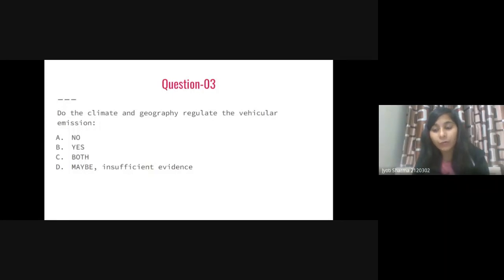But if you have lower temperature, then your NOx will be reduced, but your carbon monoxide will be higher, because there may not be sufficient combustion, like there may be incomplete combustion at that position. So if we are talking about carbon monoxide and nitrogen dioxide, then they will be opposite to each other in the summer and winter.